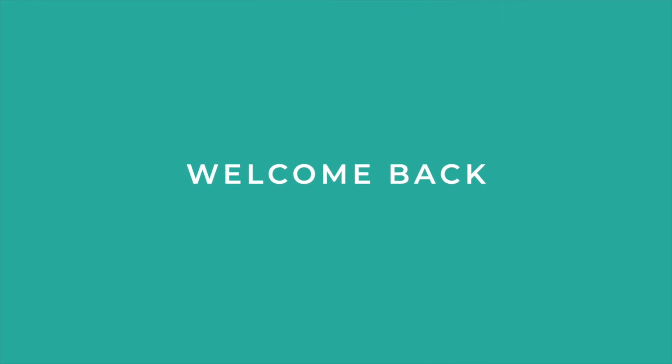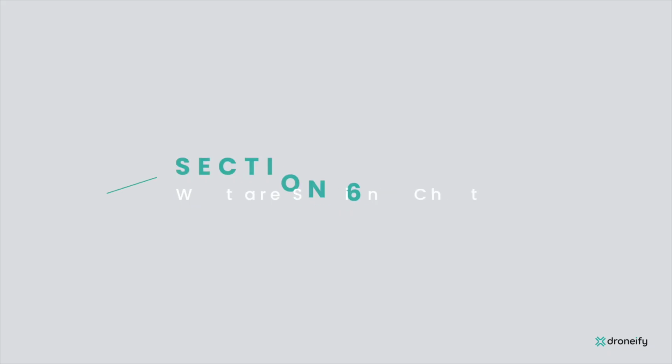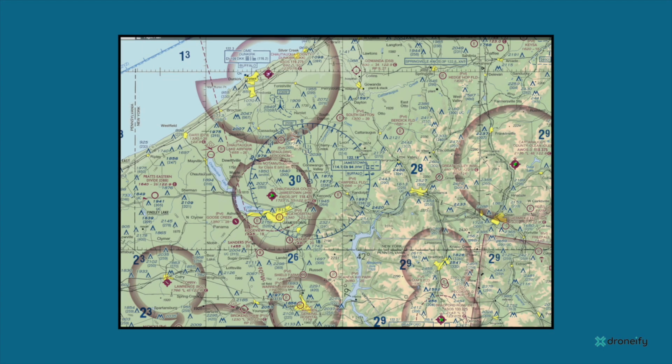A sectional chart is a type of aeronautical chart published by the FAA that provides detailed information about airspace and ground features within a given geographic area. Sectional charts are used by pilots, including drone pilots operating under FAA Part 107 regulations, to plan flights and navigate the airspace. Sectional charts cover a specific area and are typically printed on a scale of 1 to 500,000, meaning that 1 inch on the chart represents approximately 8 miles on the ground.